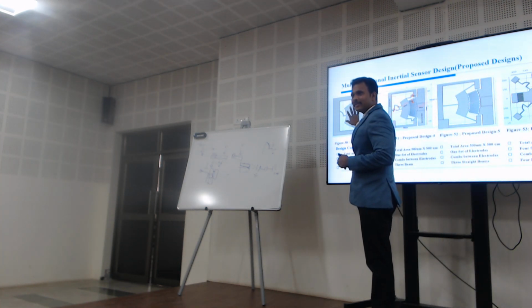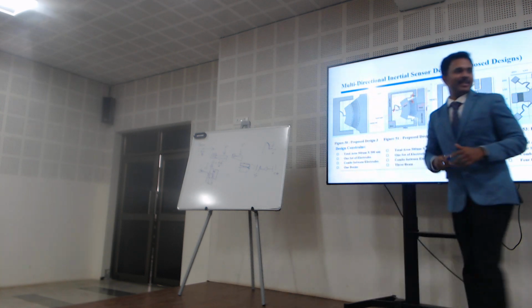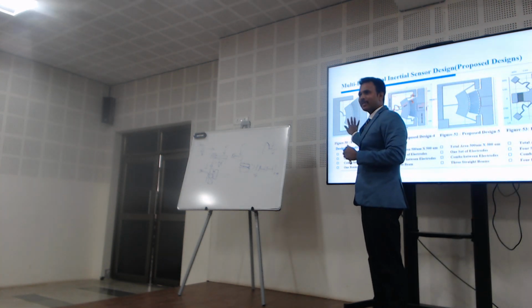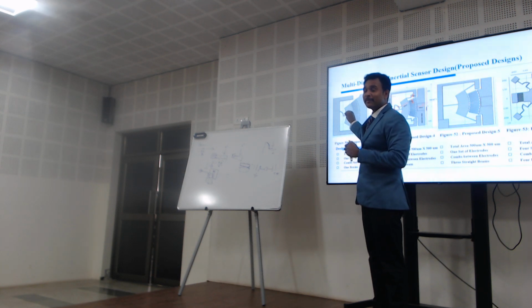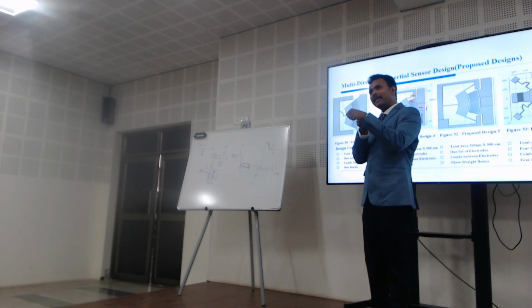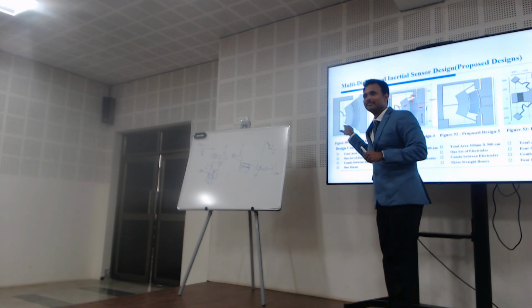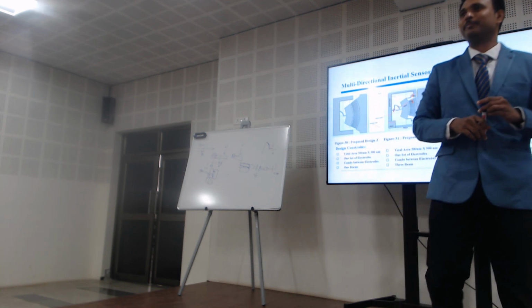This proof mass is supported with only one suspension beam. Okay, I am telling now, if I am using my mobile while walking, while traveling, at every time the same kind of gravitational force will come. Yes or no? So for small gravitational force it is okay. If any high gravitational force comes, it will bend like this and it will deform these combs. That is the disadvantage there.